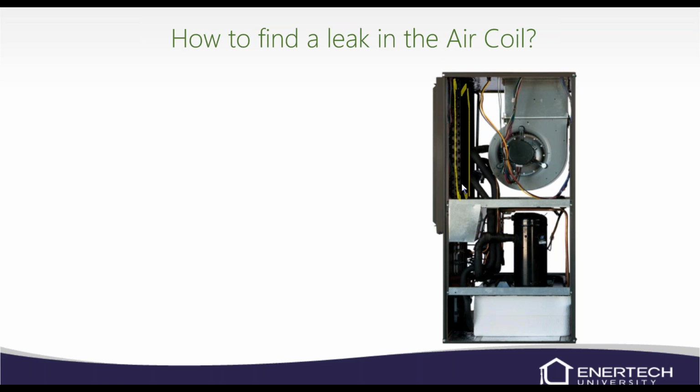If it's not leaking there, we have a fitting, as this coil is all aluminum. So it's got a little stub that's pressed in, and on that stub, there's like a little black piece of plastic, and there's aluminum to copper going together there. And so we put that plastic over there so air can't get to it.